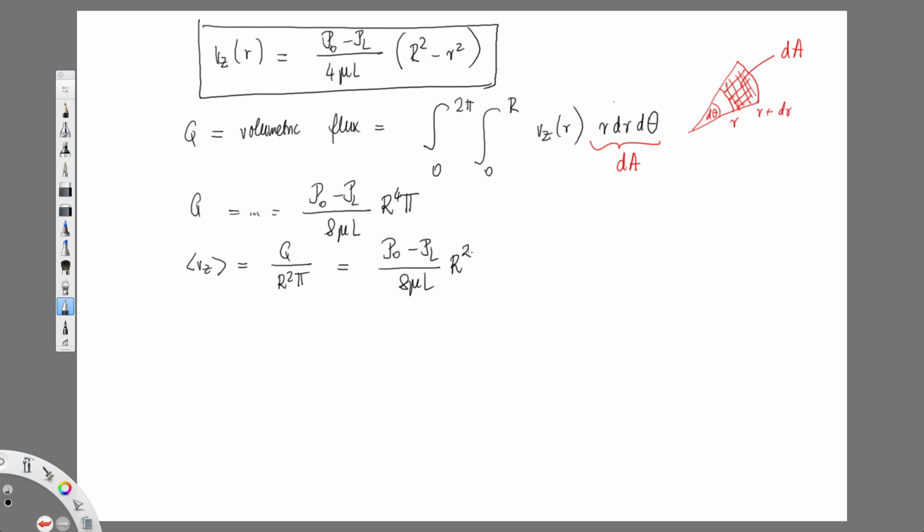So it's how I apply boundary conditions that actually specialize things further. And then this velocity is dependent on the assumption that I have a Newtonian fluid, because I took the expression for tau that is for generalized Newton law. If I had a different expression for tau, that would make things a little different, because it wouldn't be just derivatives of velocity, but there might be dependence on velocity itself or its powers and so forth. Then it becomes much harder to integrate. But again, I can still pose the problem for any non-Newtonian fluid. So we have fundamentals for everything.